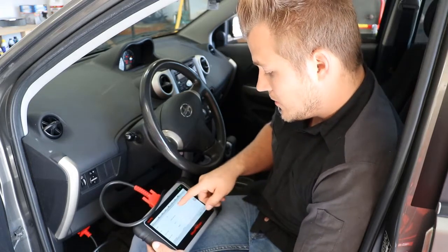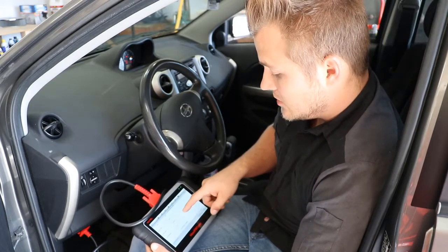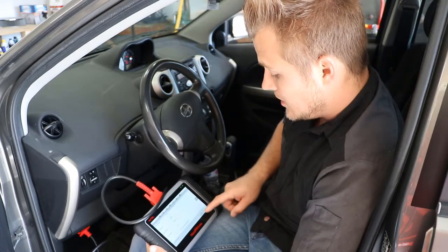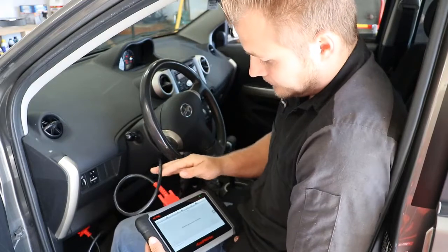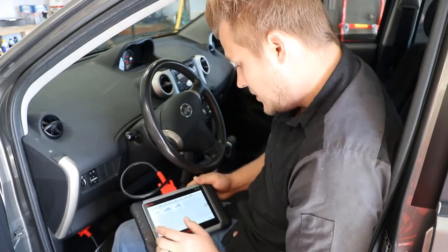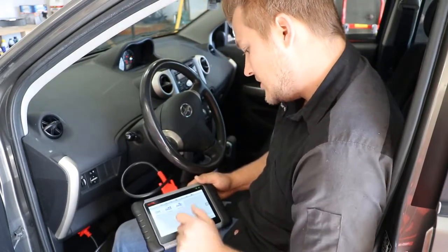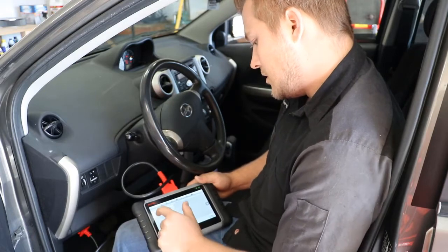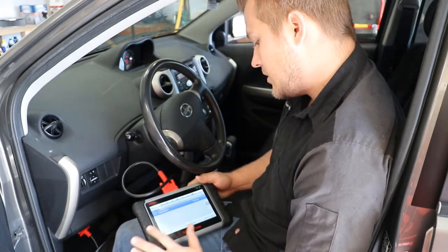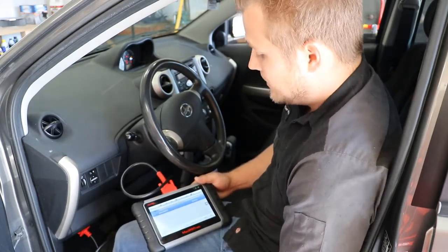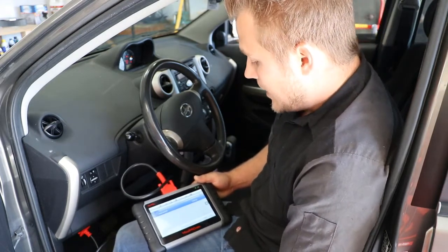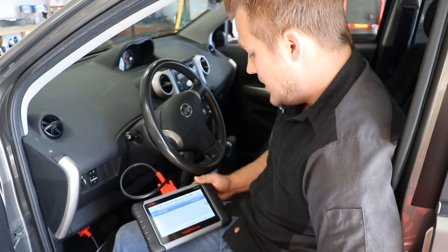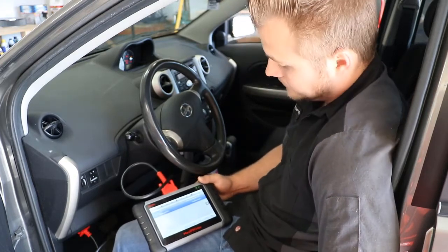And we have everything. North America, XA, NCP 2005, automatic transmission with the VIN. Yes, this is our car. And now it's going to establish communication with the vehicle. Now, first thing we're going to do is go to Diagnosis, then Auto Scan. You know what, we're going to select everything. It's going to auto scan everything, giving us all the codes so we can figure out what's going on with it. Right now it's running the engine and ECT, reading all the codes.